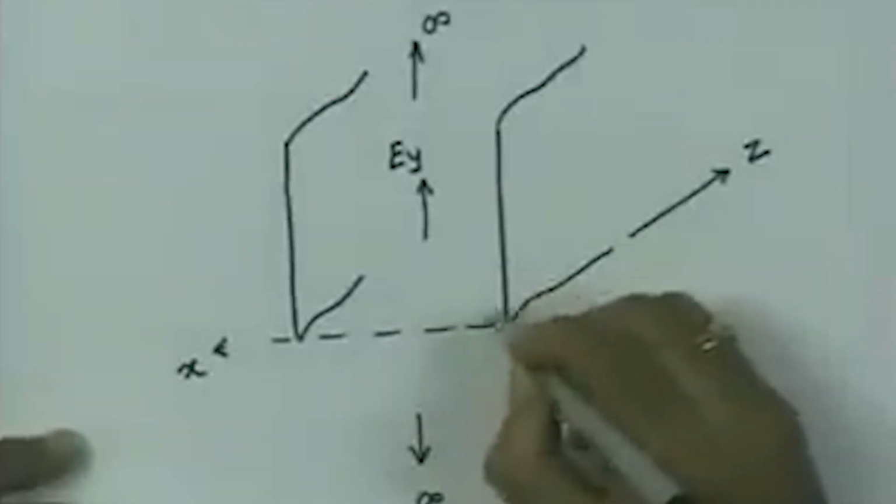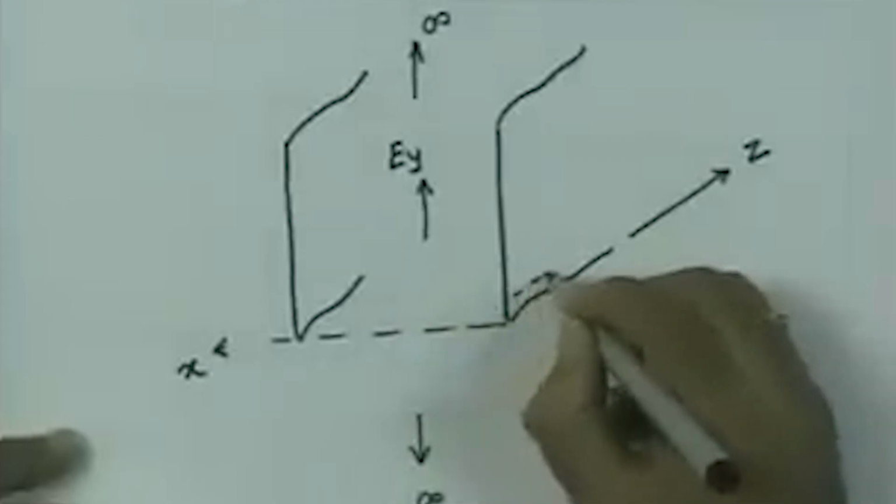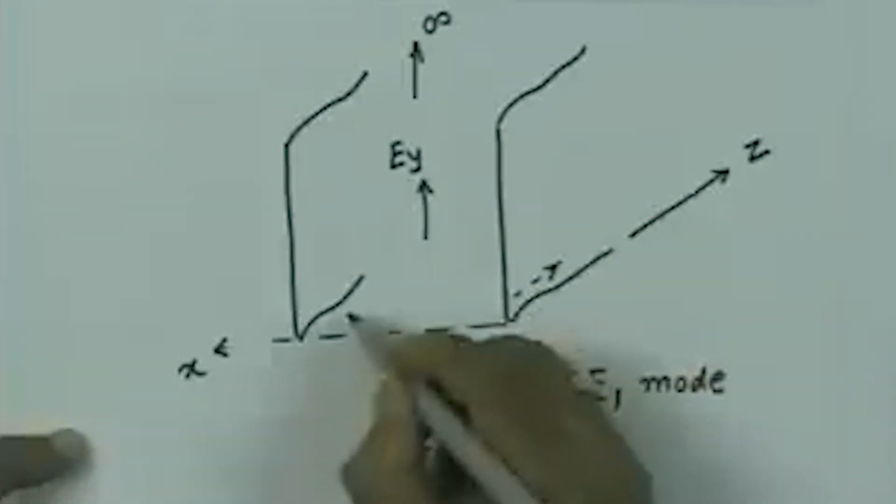So, that means if I take this as plus direction, so here I have a magnetic field like that. On the opposite wall, the magnetic field will be this way, this is the cosine function. So, z equal to this quantity, this variation as a function of x. So, if I plot this, this is the one which in the x direction is going to be like this. In the z direction, the variation is periodic with lambda g, but in x direction this is maximum at x equal to 0, at x equal to a with opposite sign, and 0 at the center.